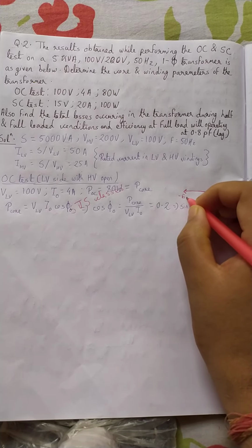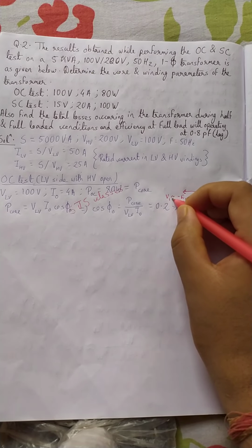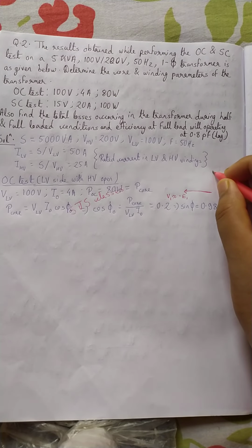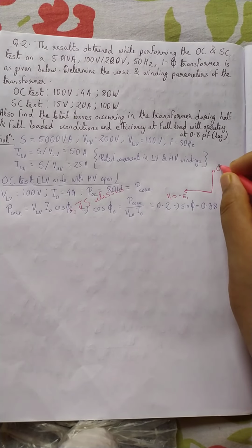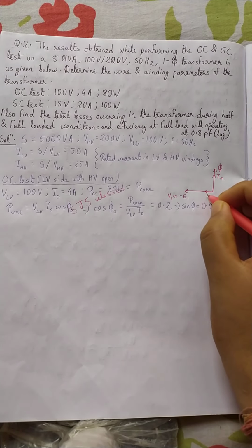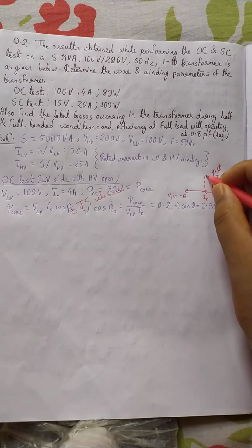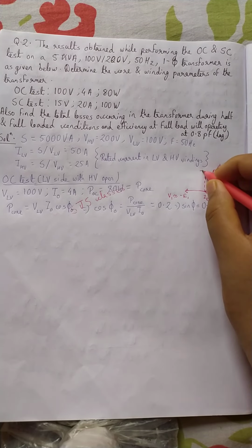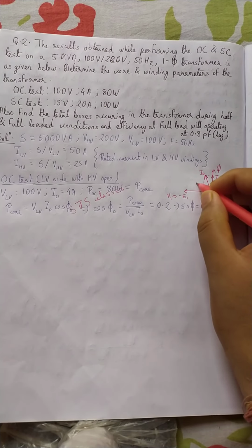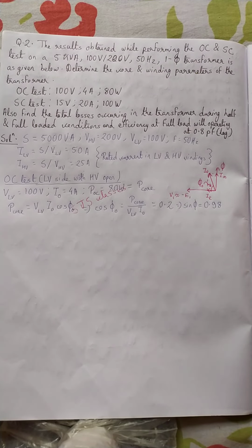This is minus E1, which we had considered to be approximately equal to V1 here, and there is some flux phi here, there is some magnetizing current Im here, there is some loss component of current IE here, and the vector addition of the two is basically I naught, and this angle we are calling phi naught.